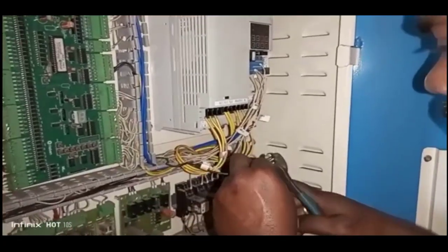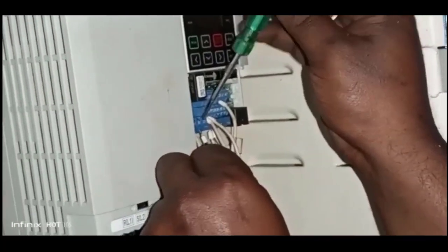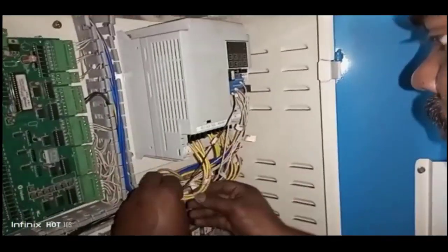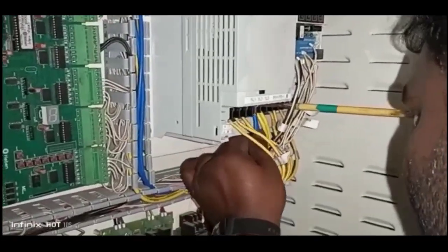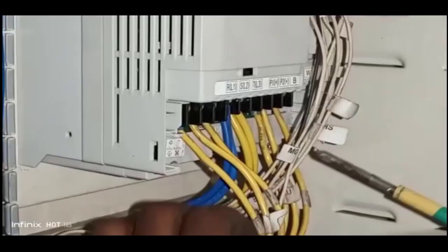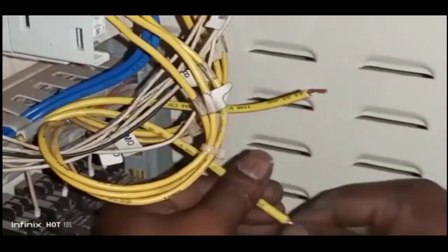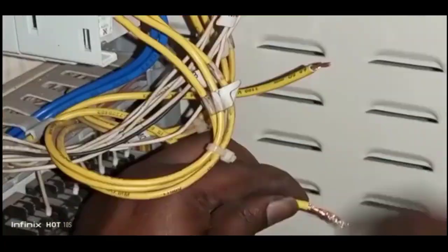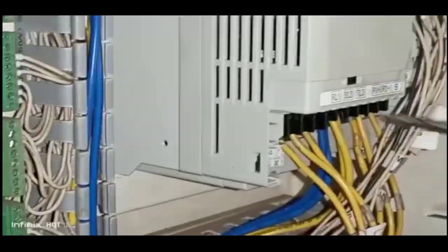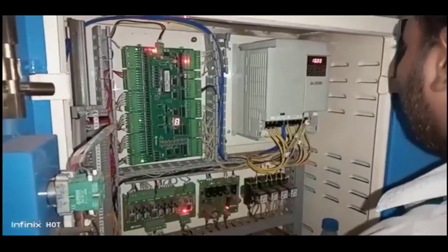He simply changed the settings in this driver board, nothing but a control block, which decreases the speed of the induction motor during running as well as stopping. The remaining wires are coming from the microcontroller which is fixed aside of this board. Not only running the motor, it has to take a lot of decisions, so the microcontroller is placed.